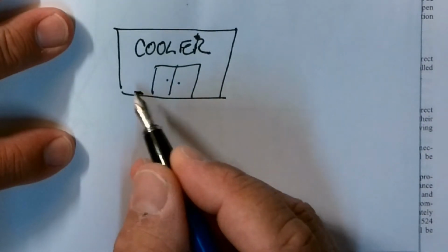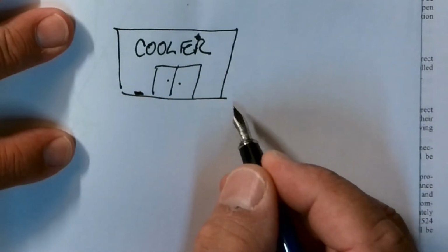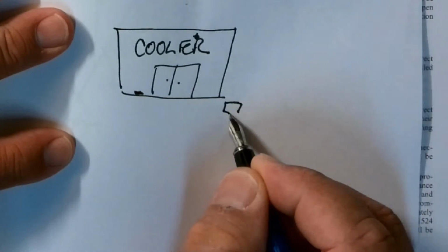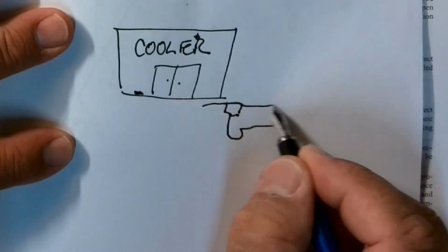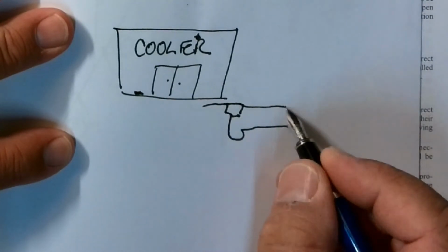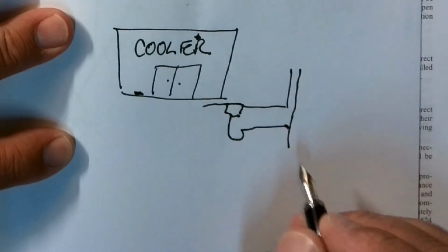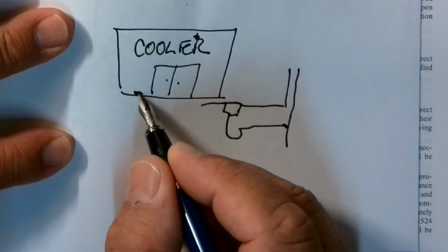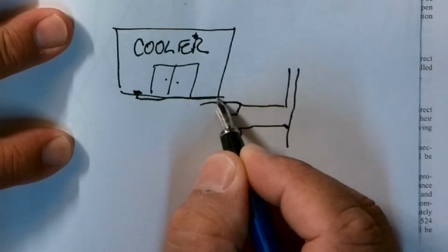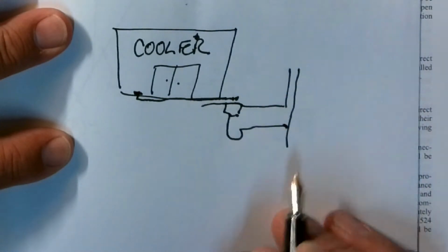Well, this floor drain, everything dumps out, runs out. You can take it to a receptor. So let's put a floor sink, excuse me, right here, and that goes over to a wall, and that gets vented accordingly, right? So this is our floor sink here. I can take this and run it all the way over to here and dump it in there, okay?